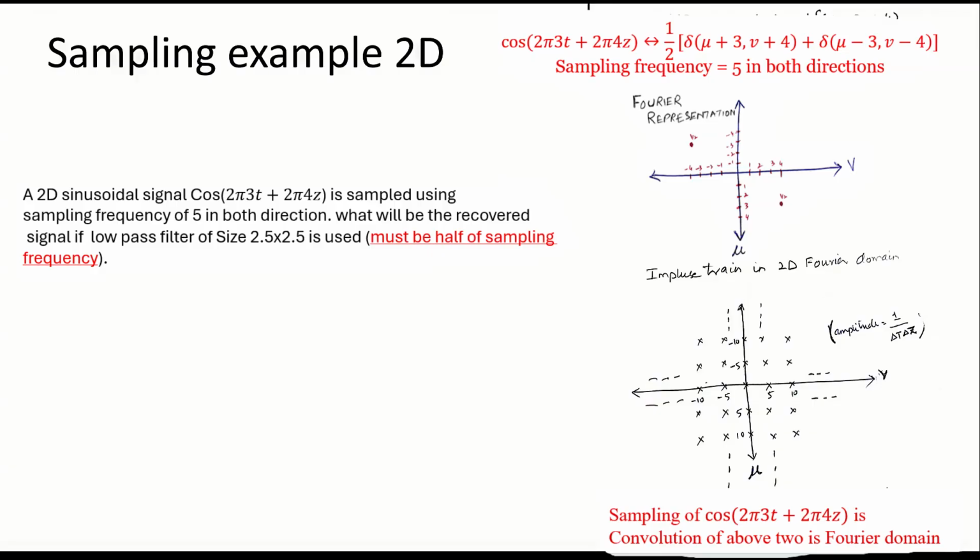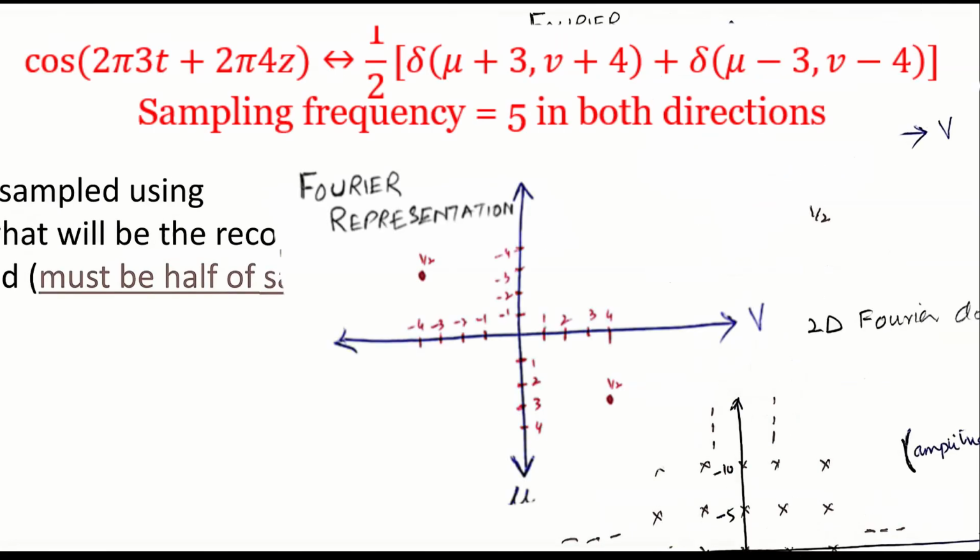So the similar example that we solved there, I'm solving in 2D. If you remember what sampling does in 1D, if I take the samples, I'm basically multiplying by an impulse train, and converting to the frequency domain. If you remember that example where you have a rectangle, what was happening? It was replicating over the impulses. The same thing we can do here, and we can see what undersampling gives us. Just be with me, hopefully it will be easy.